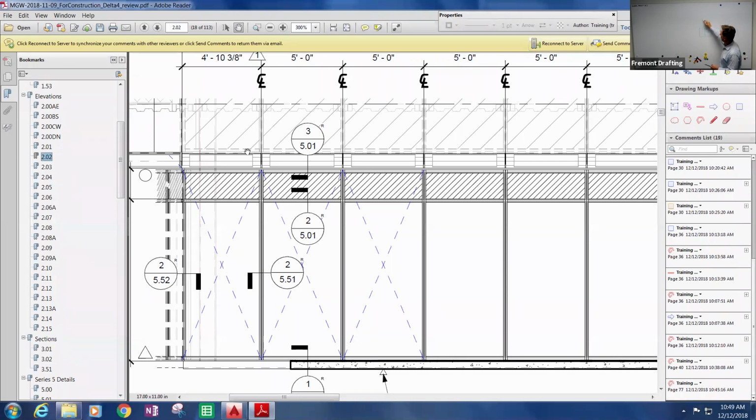This one is lifted off. This hook lug is lifted off its bolt, but it's still engaged with the vertical adjacent to it, so it can't come out. And now the dead load is really just on this one hook lug on this bolt. And then the same thing here. This unit has come off of that one, but its dead load is still there and it's still engaged down at the sill.